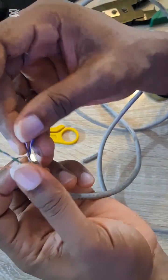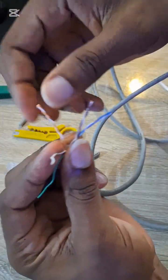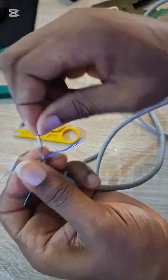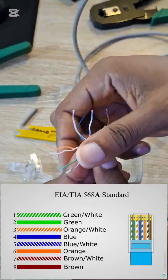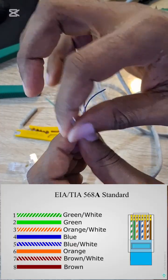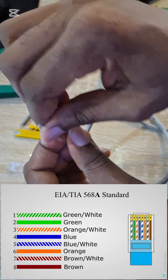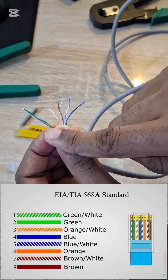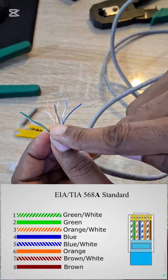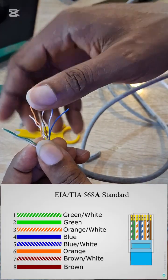All right, so we're starting with type A. Let's separate all of them first. Type A color code is white-green, then solid green. Remember, white-green first, then solid green. You hold it this way. This is how we're going to arrange all of them till we get to the last color.